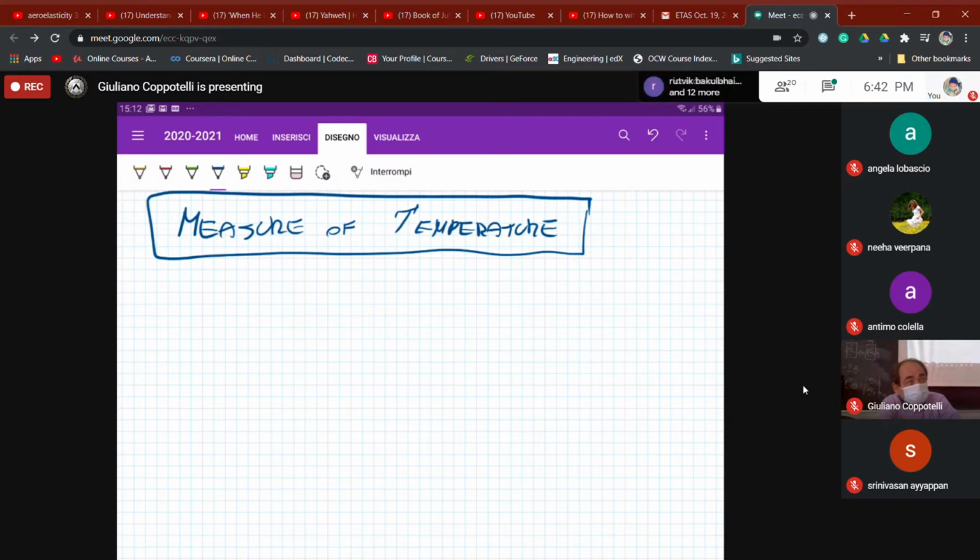The sensitivity with the maximum dissipable power that we can have in our measuring circuit, and the maximum power has to be introduced, because if we increase too much the input voltage so that we can increase the sensitivity, then we can melt everything because we overheat the measuring device.